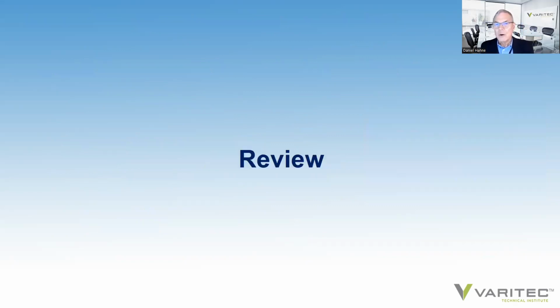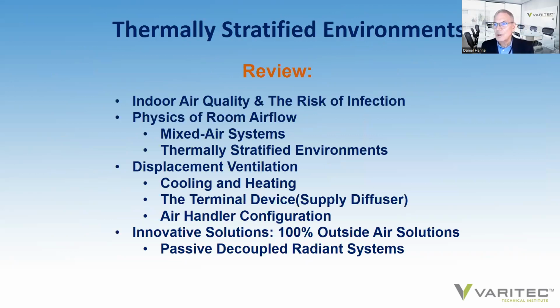So quickly in review of today's presentation, we covered indoor air quality and the risk of infection as proposed by the ASHRAE article in 2021. We looked at mixed air systems and thermally stratified environments and why convection is conducive to a cleaner air condition at the breathing zone. We looked at displacement ventilation, the HVAC strategy to create thermally stratified environments, and how it might be applied both in cooling and in heating, and the type of devices utilized to create the necessary indoor air environment.